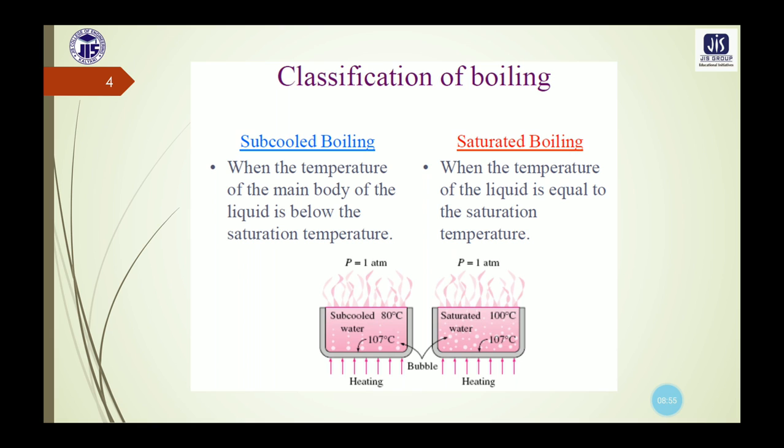At the liquid solid surface, the vapor bubbles are formed, and after forming they propel through the liquid by buoyancy effects. After a certain amount of time, they escape from a free surface, that is the liquid vapor interface. So this is the concept of saturated boiling.